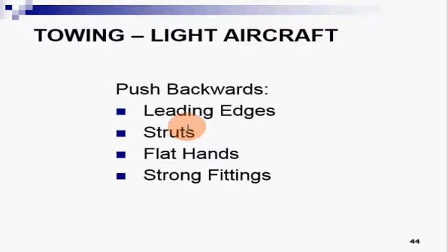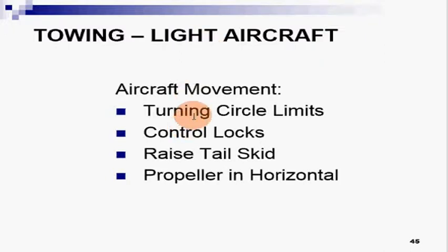So there are some techniques which are related to the pushing of an aircraft. Always push backward. Always push backward from the leading edges. Struts, always use the flat hands. Strong fittings should be used for the pushing of an aircraft, and these are the valuable kind of information related to the pushing of an aircraft. So always follow these instructions for a better pushing or a better towing of an aircraft.